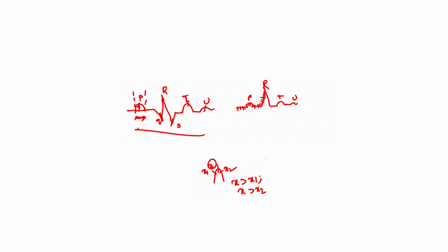If I do that in an algorithm, I can easily find out how many peaks I have in the ECG signal. In this case we have P one peak, R one peak, T one more peak and U one more peak, but I may not require all the peaks, I require only the R peak. But how do I differentiate which is a P peak, which is an R peak, which is a T peak and which is a U peak? It is very hard to differentiate, but if I can pass only the peak of R by neglecting other peaks, I can get only the R peak, and if I count how many such R peaks I am getting with respect to 1 minute, I can easily calculate BPM.